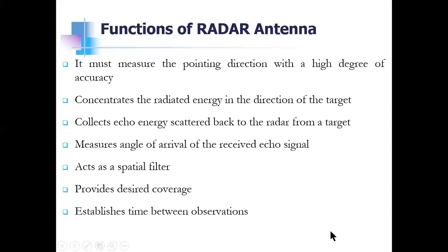But the total power which is sent by the transmitter should be proper, though the transmitter is small. Okay. Now we all know there is an equation G is equal to 4 pi AE by lambda square. In that equation, we know that the antenna gain, that is G, and the effective aperture, that is AE, are directly proportional. So as you increase the effective aperture, your gain is going to increase, right? So that's why we say that we need a larger area of the antenna. G is equal to 4 pi AE by lambda square, right? That we have studied since last year, right?